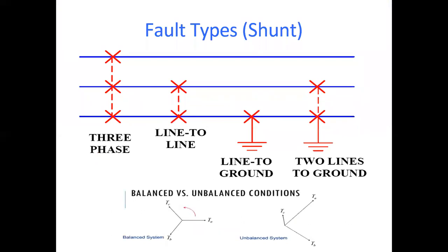The fault types. The first one is the line to ground fault, in which one line somehow touches the ground or a support. The second one is the line to line fault, in which two lines are connected together due to insufficient distance or wind pressure. The third one is the double line to ground fault, in which two conductors touch together and touch the ground or pole or tower. Then the three-phase short circuit fault, in which all three lines make contact in abnormal situations such as storm or falling of a tree.